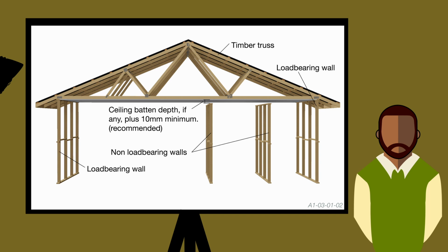They are there to separate spaces, and you can use 2x4s up to like 12 feet or something. And the idea is nothing's depending on them, right? But another problem with using 2x4s for those long spans, if you have like 11, 12-foot ceilings, is finding straight 2x4s.